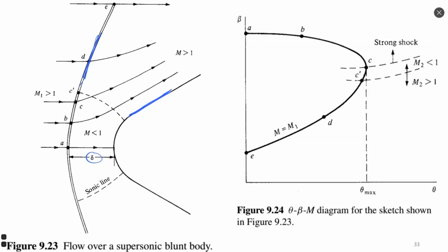the shock wave is mostly caused by the straight slope. So we could probably calculate it using the theta angle, and we could calculate the beta angle and maybe some other properties. Maybe. But I was thinking maybe it was similar to the case when we had a conic section instead of a wedge, and the velocity change wasn't instantaneous. It had a curve after the shock.